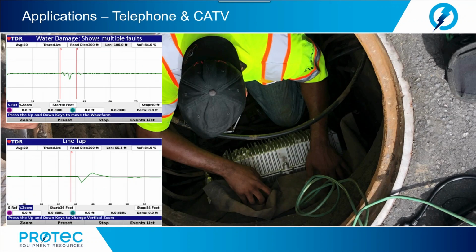Now, for telephone and cable TV applications, water can seep through the conductors of a twisted pair cable at multiple ingress points along the insulation. In these situations, testing the cable from both ends and recording the distance to fault will give the lineman an accurate illustration of the severity of the water issue or confirm that the initially spotted abnormality is correct.